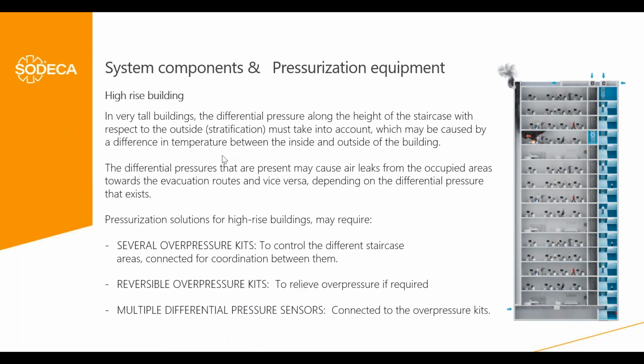Okay, the last point to consider about key points of the pressurization system is for high-rise buildings. Typically, for standard buildings, the standard gives general provisions for the design, but for high-rise buildings, we have to consider that there is the risk of the stack effect, because due to the different temperatures inside and outside of the building, there is a possibility that the higher parts of the staircase have higher pressures compared with the low parts of the staircase with low pressure. So there could be leakage of air from the protected area to the accommodation areas, or the opposite, depending on whether we are talking about winter or summer.